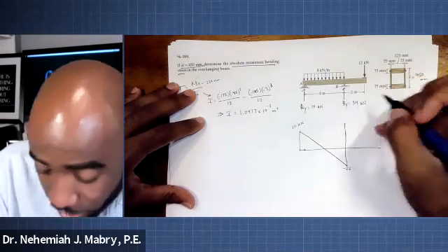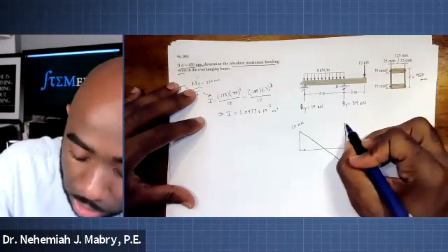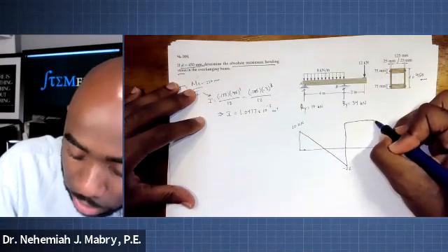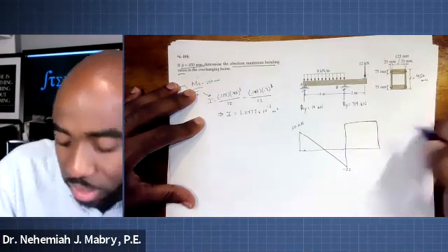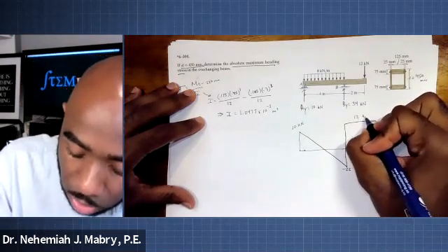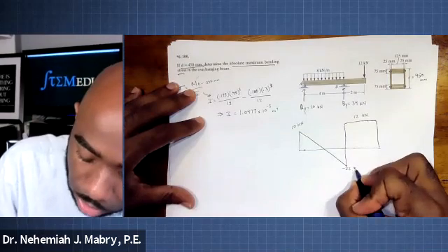Again, right in line with that. Then nothing's taking place, so it stays constant here, and then there we have it. Our 12 is going to, I made it a little longer, so I'll go ahead and come back down here. Boom, our 12 is going to bring it there. So this is 12 kilonewtons. This is a negative 22 kilonewtons.